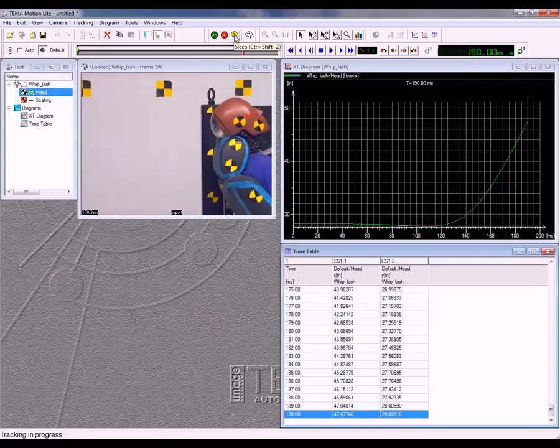If the tracking is lost, as noted on the bottom left of the screen, you can manually place the point. But note that after manually placing it, later automatic tracking will not overwrite this manual placement.